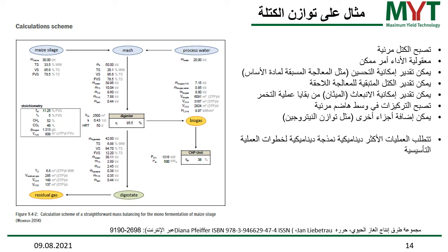We have a certain mass of biogas going out, and the digestate is essentially the mass of substrate minus the biogas. And then we have total solids, volatile solids, all the fractions which are left in the digestate. And we have, of course, a certain residual gas potential in the digestate, because the process with a given retention time cannot convert 100% of the gas potential.